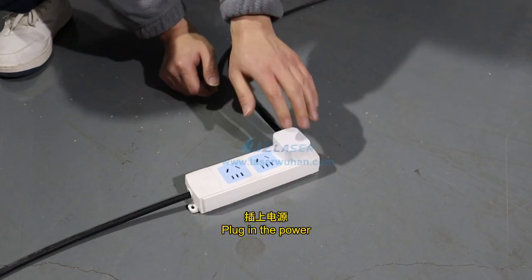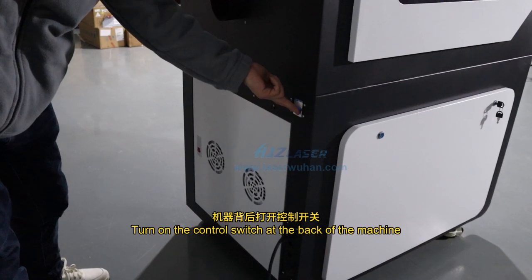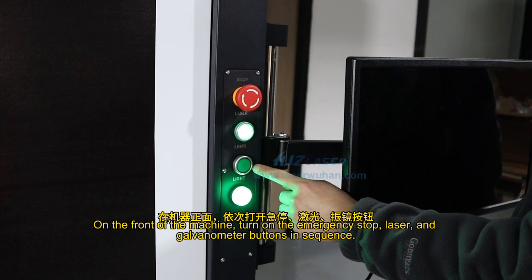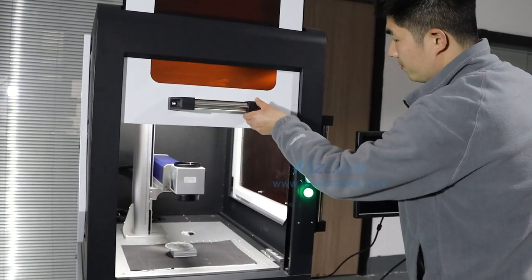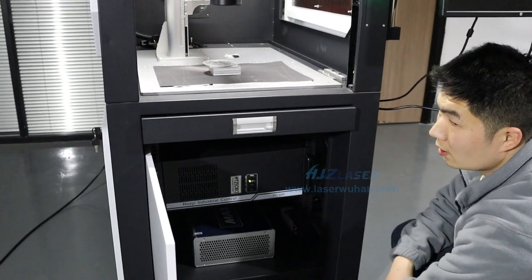Plug in the power. Turn on the control switch at the back of the machine. On the front of the machine, turn on the emergency stop, laser, and galvanometer buttons in sequence. Open the dust-proof lift door. Open the computer in the cabinet.